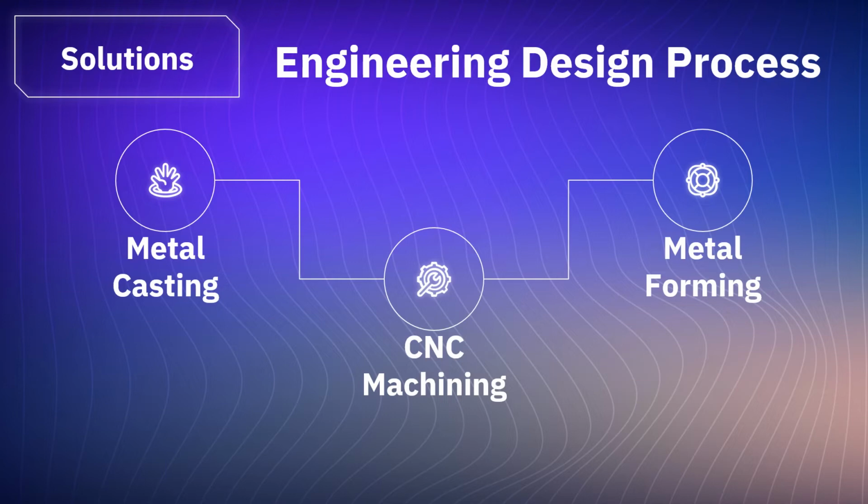In this process, the molds are usually made from foam, plaster investment, ceramic shells, or resin-bonded sand. The process is still in use due to being inexpensive and relatively fast. Therefore, for small volume manufacturing, expandable mold casting is the best option. However, in our case, we're going to be choosing the non-expandable molds since they are permanent and reusable.